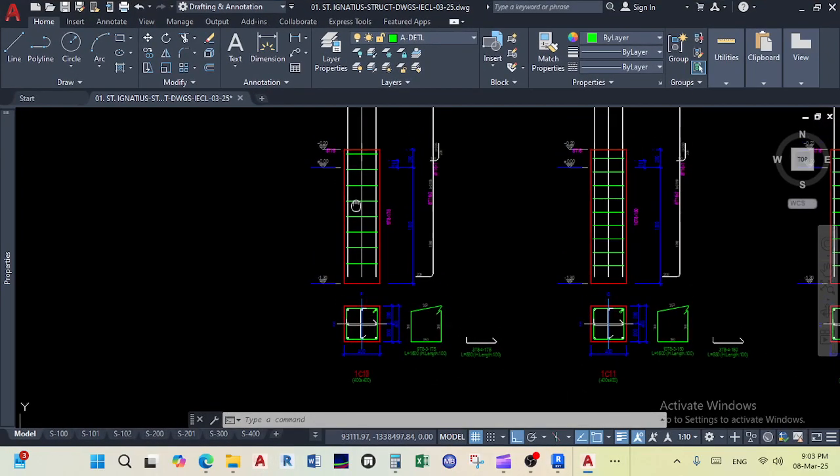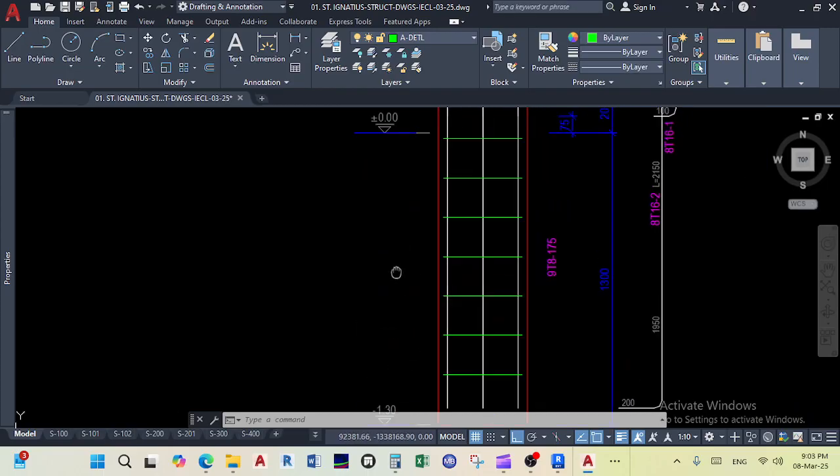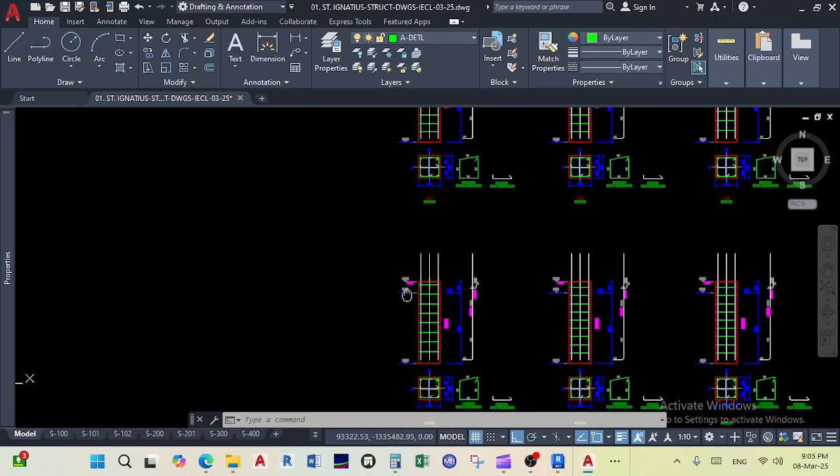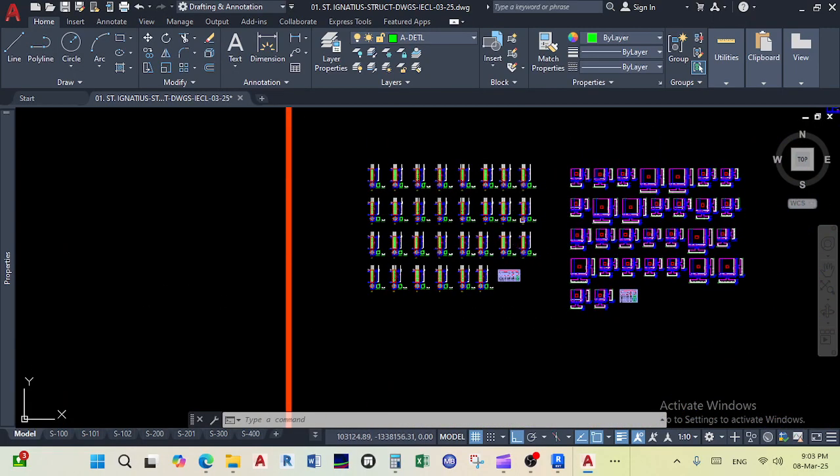When you open it, here it is, the math. It shows you that you are creating a step of 200 to just prevent water ingress. This will be your ground floor, meaning if you've got extreme conditions of water here, at least this curtain will be able to ensure that water is not entering the room, as opposed to if the slab was just here. So it gives you information.